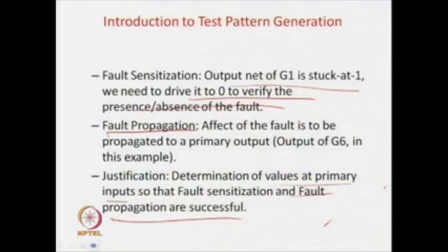If you do this for all the faults, you are going to get the test patterns generated for all the faults. Now, when all the test patterns are generated, they are stored in the memory. When this IC is fabricated and comes from the fabrication unit, for each IC you have to apply those inputs and verify that none of the target faults are present. If all the test patterns verify that there is no fault, you can say that your circuit is free of stuck at faults and it can be shipped to the market.